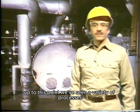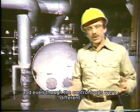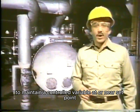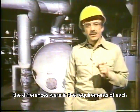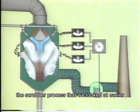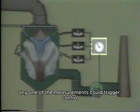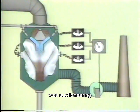Up to this point, we've seen a variety of processes and the different control loops used to maintain each. And even though the control loops were different, they all had the same objective, and that is to maintain a controlled variable at or near set point, or provide a corrective action when the variable reaches a preset value. The differences were in the requirements of each process. For example, the scrubber process that we looked at earlier required that gas temperature be monitored at several locations, and that any one of the measurements could trigger control action. The control loop that we described for this process was auctioneering.